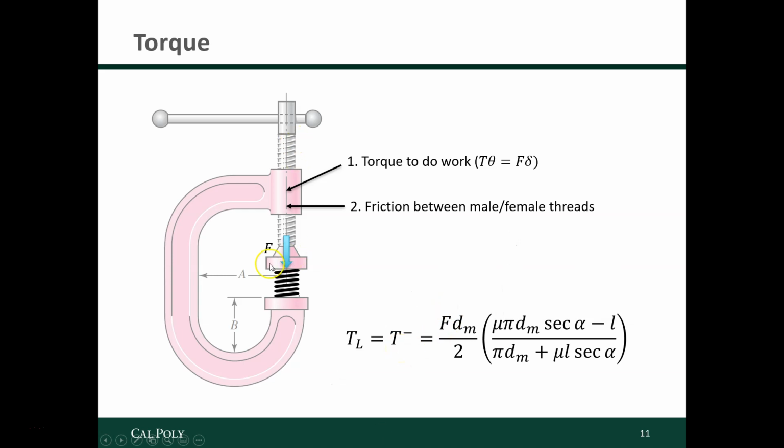If we were letting the spring decompress, if this interface were moving upwards and the spring was expanding, then the force that we are applying on the spring is in a direction that's opposite the displacement. And so this is the same as, say, lowering a load. We're doing negative work here. And we've got all the same variables. The only thing that's changed about our equation is that there's a sign change in two places.